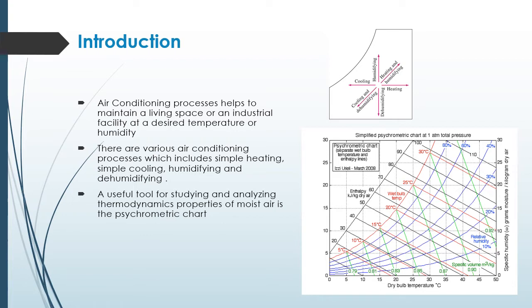It displays the properties of air, like dry bulb temperature, the vertical lines, labelled below as you can see. After that, wet bulb temperature is a red line, sloping gently downward to the right. Also our dew point temperature, the horizontal lines in the figure, and relative humidity, the curves of the chart.